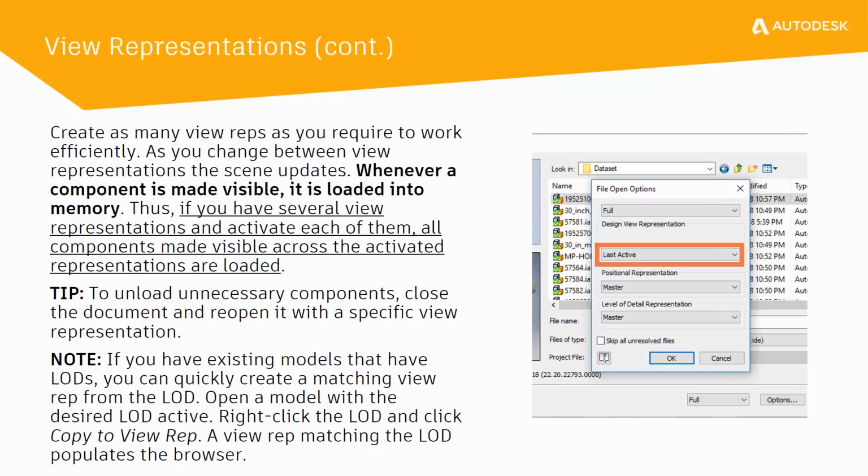The way that you can unload unnecessary components is to close the document and then reopen it with a specific view representation in mind. You can do that from the open dialog by going to the options, selecting the design view representation that you want to use, and then clicking OK and then open, and that will open that specific design view.